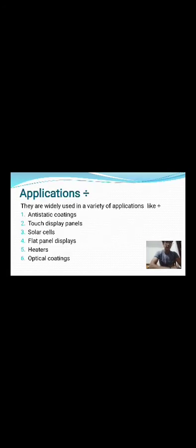Transparent thin film inductors are hard to realize due to poor conductivity, and a high inductance requires a large number of turns, which in turn results in increased parasitic resistance.